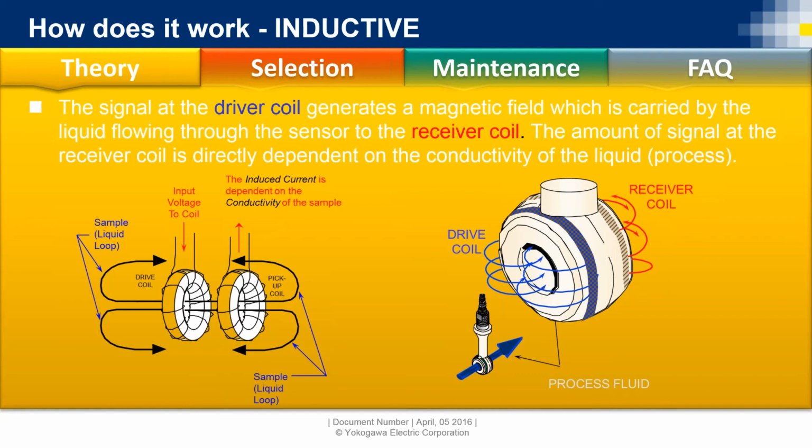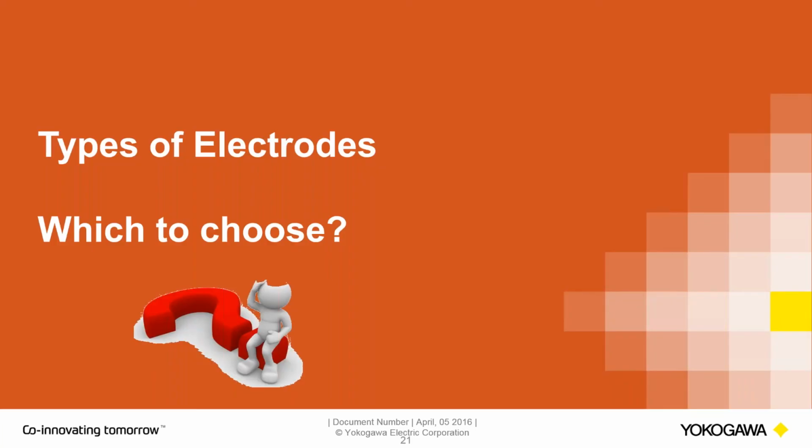If you're in something that's 100,000 microsiemens solution or 1,000 millisiemens solution, that one more microsiemen is not going to make a big difference. But if you're in ultra pure water, where you're less than 1 microsiemen, an accuracy of adding 1 microsiemen is a big influence to you.